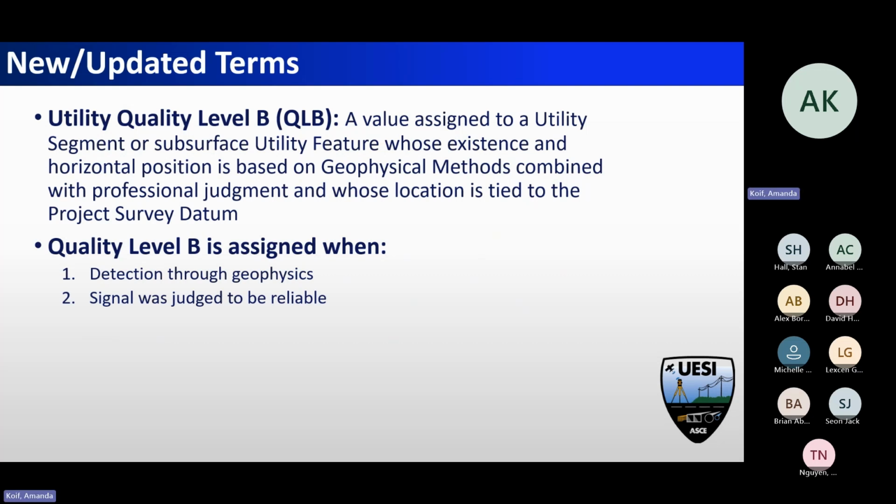The signal was reliable. Hopefully your field staff are trained and understand that just because they're on a signal, getting a tone on the line, doesn't mean that's the line you're looking for. It could stray off and bear off, back and forth, in what we call bleed over or signal interference. We actually ended up having a study on that a couple of years ago